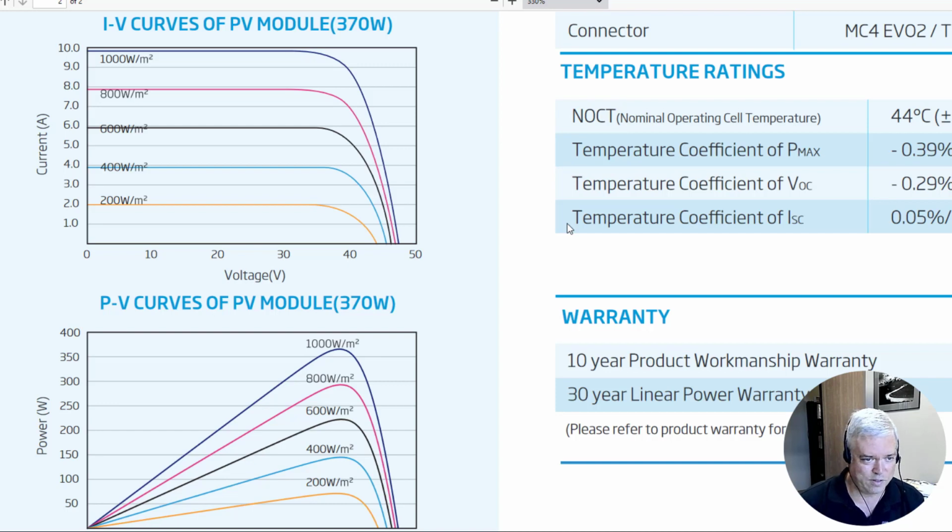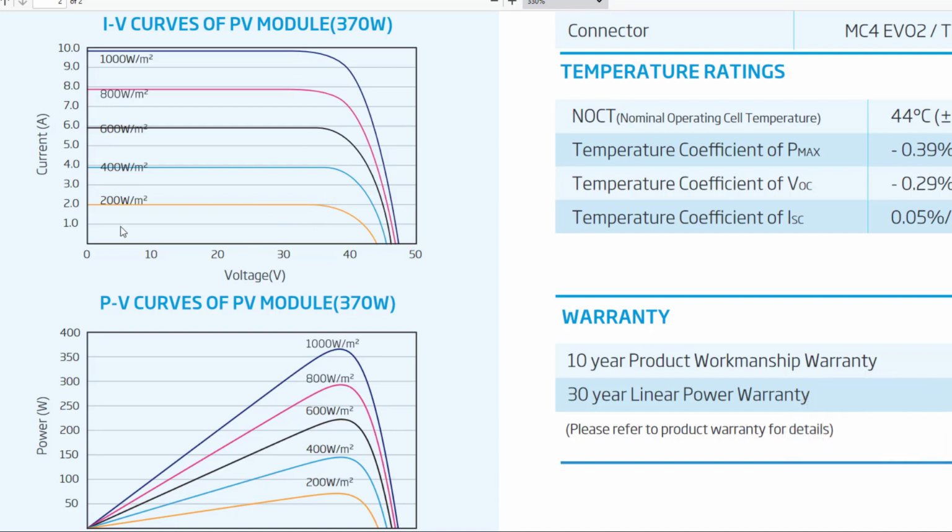energy. So at the top is the standard test condition of 1,000 watts per square meter. 800 watts per square meter will get you a different output with a peak of about 7.9 amps instead of the 9.8. So you see how all this, the voltage doesn't actually vary very much. The voltage is somewhere through here, but the current output is what rises and falls with the conditions in the field from 1 minute to the next. And that's what a maximum power point tracker is.